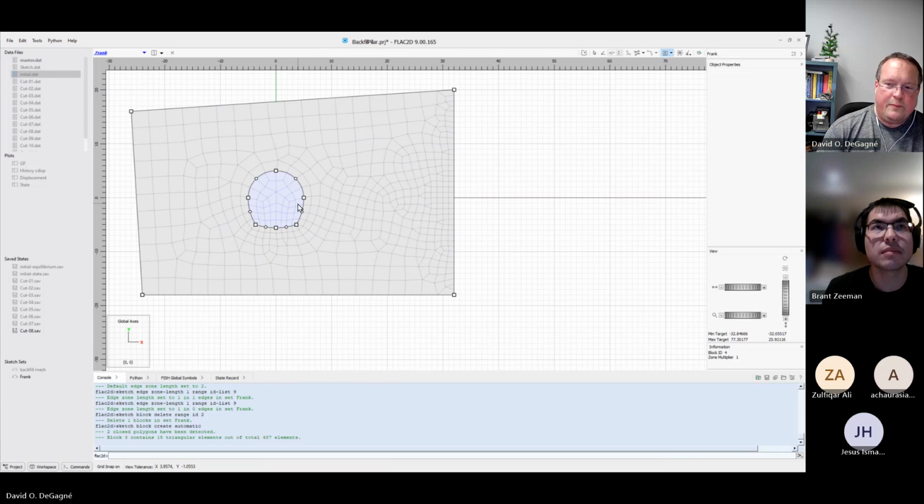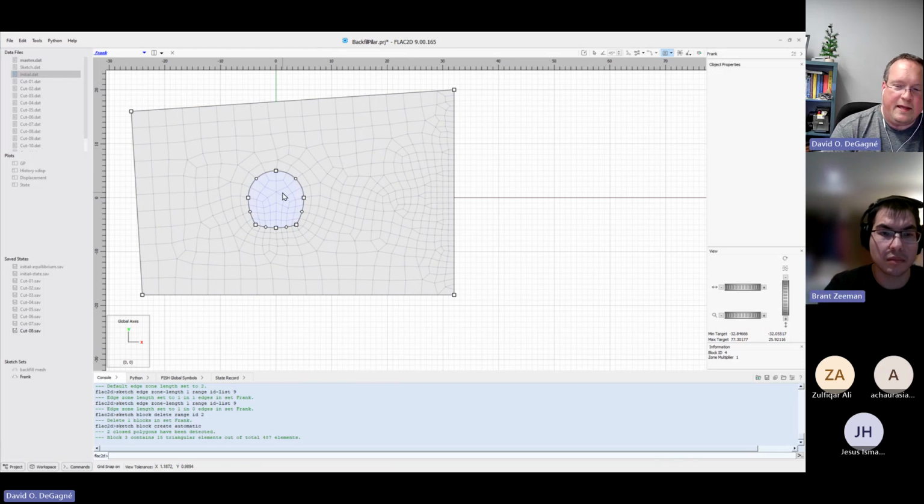But what you often will see is these sort of artificial implosions, and sometimes you want that. Maybe you're studying rock bursts or something like that, and you want to have a high rate of closure. So what we have is a relaxation command that lets us essentially pick a material, some group like tunnel, and then we can gradually over several steps relax it.